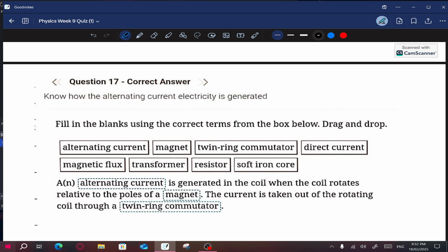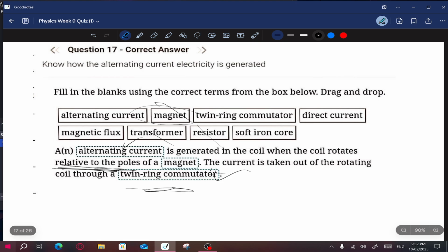Now, N is the number of turns. Let's say the secondary coil had 75 turns and the primary had 150. This is going to equal a value less than 1. If the turns in the secondary coil are fewer than the turns in the primary coil, it gives me a step-down transformer. So here, SC is less than PC, which makes it step down.